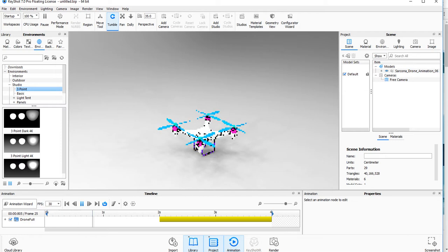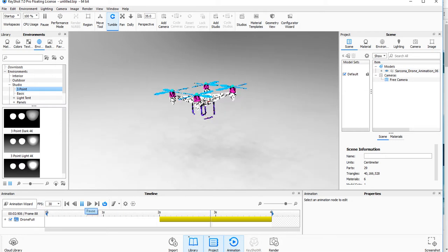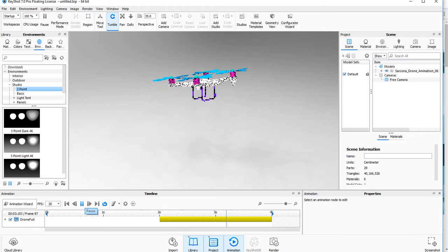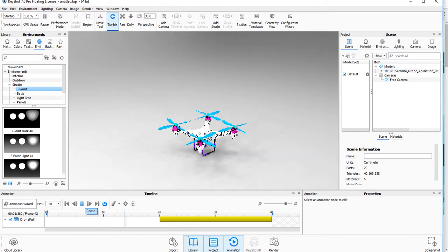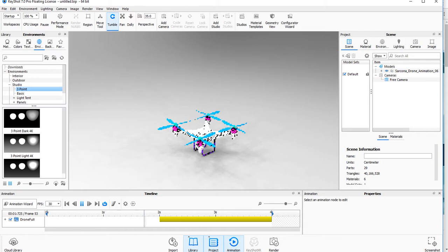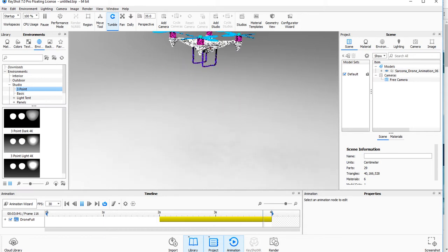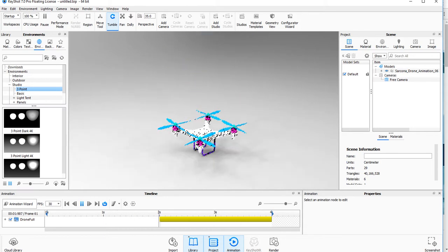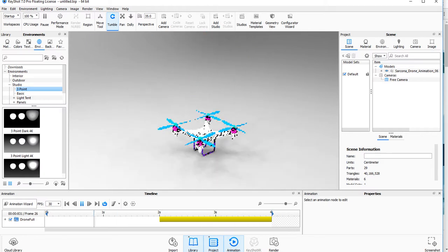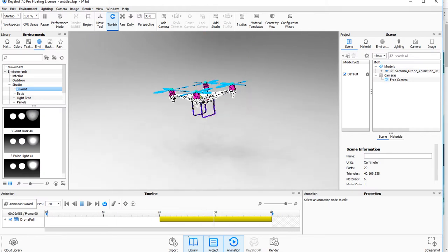So look at the animation. Verify that you like the animation. There's no point in going any further if the animation isn't working. Okay? If it shoots up too quick, or it goes very fast and then somehow slows down, or it does some blocky kind of movement, fix those back in Cinema and re-import back into here. That's all you have to do. They've simplified this process, which is another nice reason about KeyShot, it imports the Cinema 4D files directly. I don't believe VRED does that. I think with VRED you have to export it out and then import a separate file format.